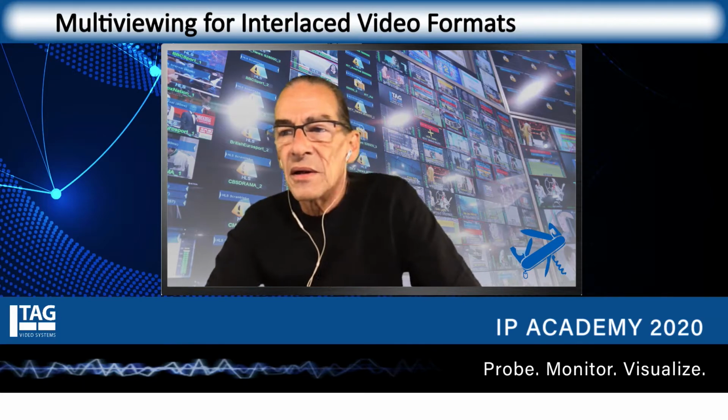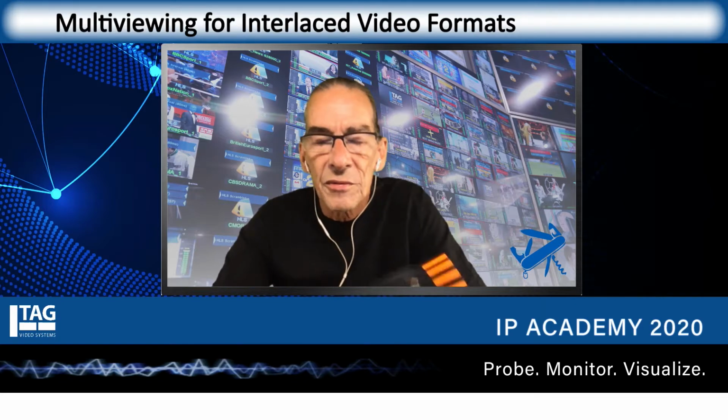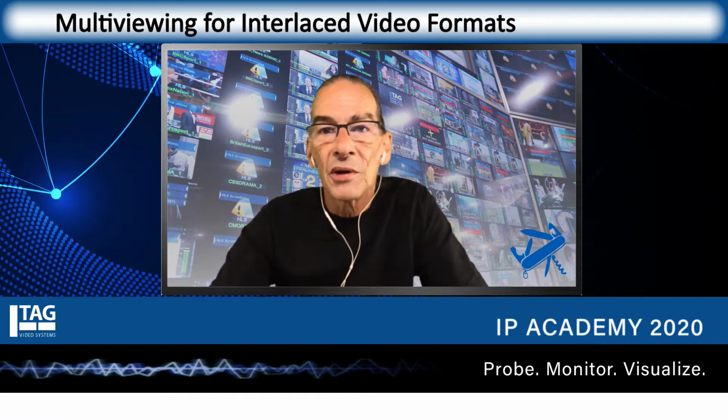So in the process of doing this very, very simplistic, very early technique, we come up with a whole bunch of challenges that have to be overcome in order to integrate that into a modern production environment where we deal with progressive pictures and we deal with evolutionary frame rates and evolutionary resolutions. We still have to somehow accommodate this stuff, and the 2022-6 standard accommodates it. The 2110 standard accommodates interlace, and interlace isn't going anywhere fast. You probably have it in your life. If you go home and watch TV, you certainly have it somewhere between you and the TV station.